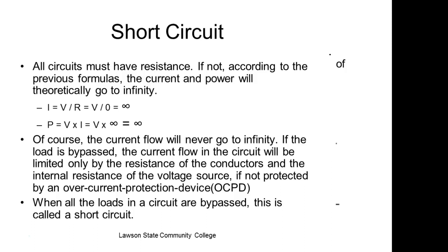What you should have done is run another circuit into it, leave the devices that are in there alone, and put the new stuff that you added on another circuit. Most houses don't use all the slots in the panel that are available.